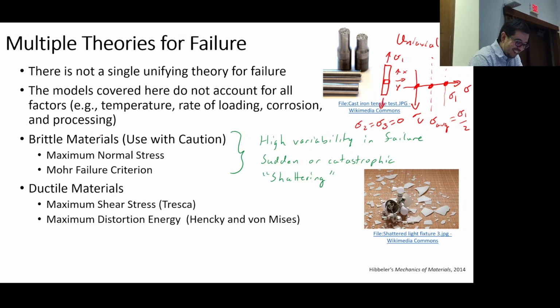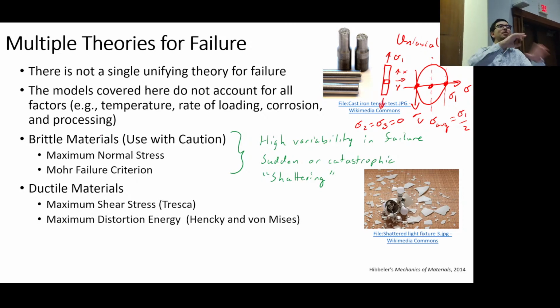All right, so now, to your point, how do I draw the circle now? Basically, the center is going to be the average, and you got to go through sigma 1 and sigma 2. Right, okay, so that's my crummy looking circle. Okay, now what is the radius? No triangles, no square root of nothing. What is the radius?